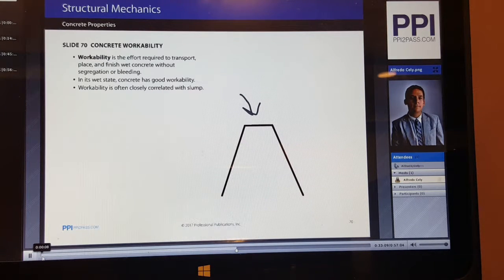So that concrete starts to fill in the cone. Now, if we remove the cone, the concrete is filled up to this point. You stir with a bar just to get the concrete to evenly distribute through the cone. Once you have stirred with a bar to make it uniformly distributed, you lift up the cone and you may find that the concrete will have a slump shape.